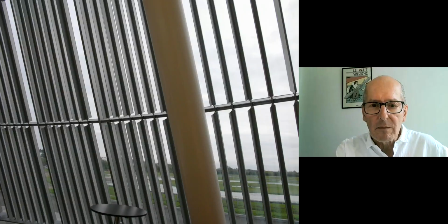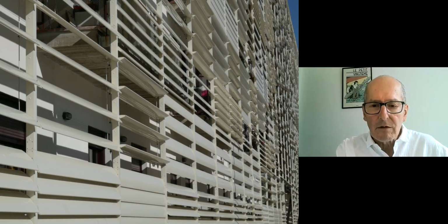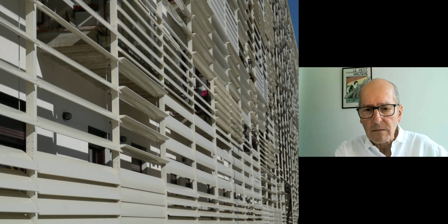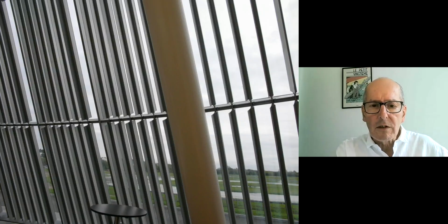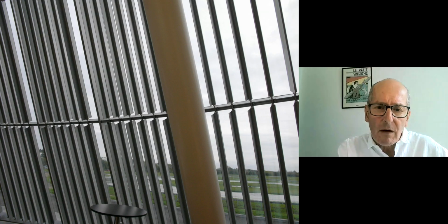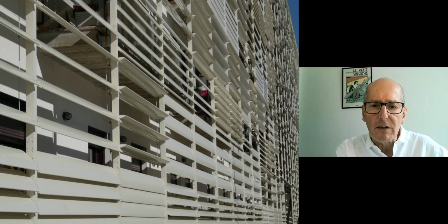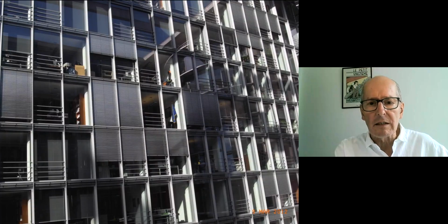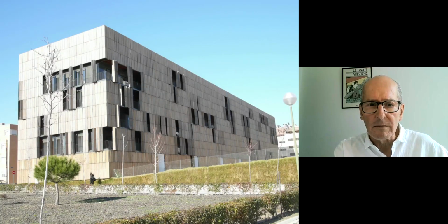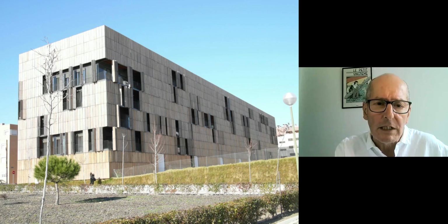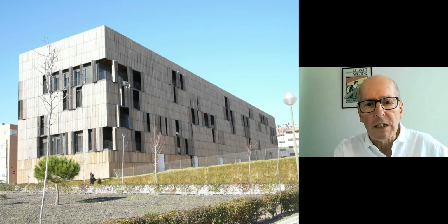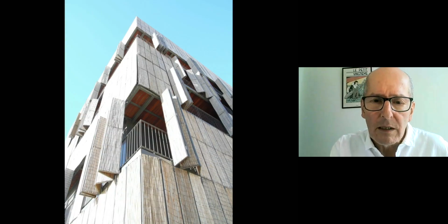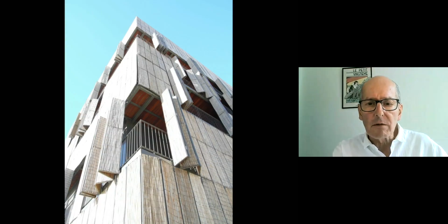Here are some examples. This is actually just to remind, a little bit over the top perhaps, but these louvers control solar gain. Of course, in the northern hemisphere, we tend to put them horizontally facing south, vertically east and west, and none on the northern side. There are some other examples. This is a rather nice one. This is in Madrid again, I think, and the whole building is ringed with these nice little bamboo shading devices which can be opened and closed.